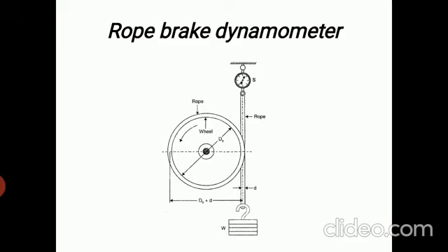So you should not overload the engine. If you are overloading the engine, there might be a chance of seizing, engine damage, or any one of the engine components getting damaged. If you are overloading the engine, it will not be able to pull the load. So you should load the engine a maximum of up to 95% of its full load while testing.